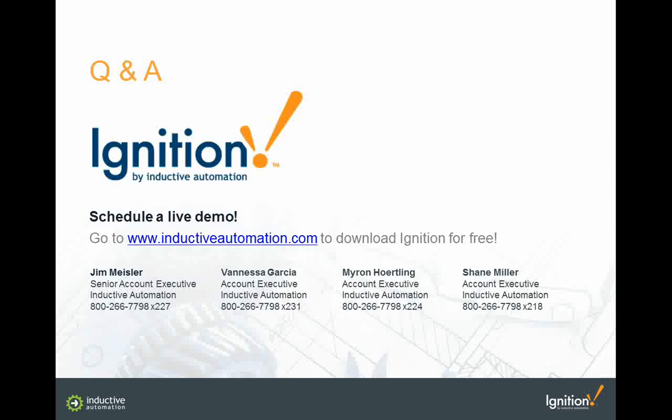Here's another question I'll ask you, Kevin. Which databases and PLCs can you connect to in Ignition? What can you connect? Well, Ignition is pretty unique in that it leverages the power of the Java platform. So it can connect to anything that has a JDBC driver, which is pretty much any database that's out there in terms of what you might actually come across at the customer side. It can talk to MySQL, MS SQL, Oracle, and all of the littler guys too. You'd be hard-pressed to find a database that doesn't have a driver.